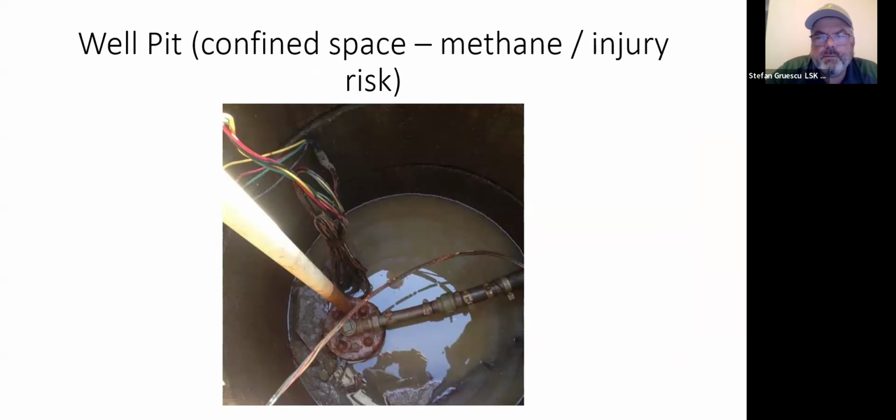Now, if you remember in the previous slide, there's something called a pitless adapter, and that's how it got its name. That's a quick connect fitting where we don't need to get down into a pit anymore. We can just put a tool from up above and pull the pump out through a quick connect fitting. So we don't need pits anymore, and they're not allowed to be constructed. You can still have one if it's existing, but we can't construct the well this way anymore.